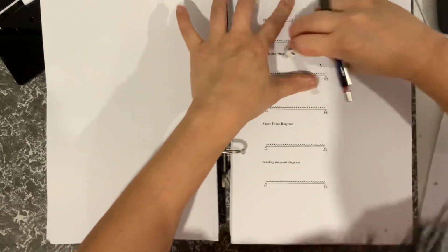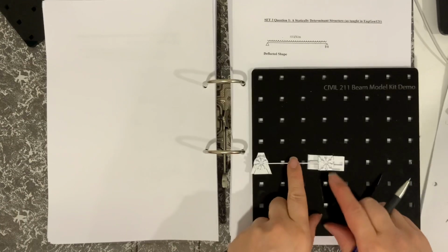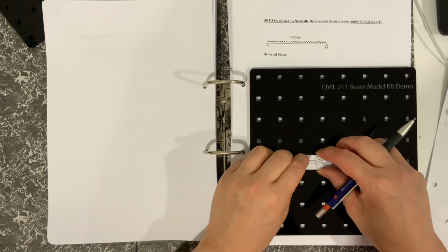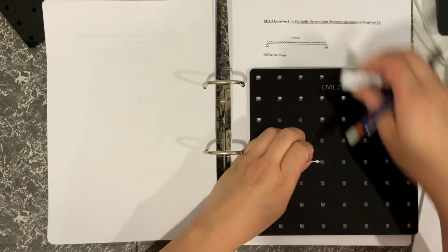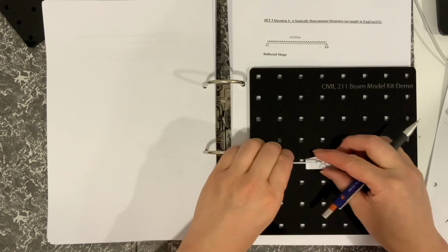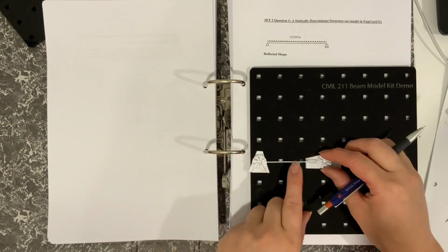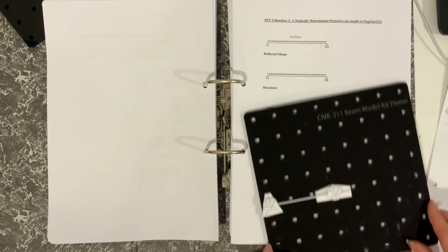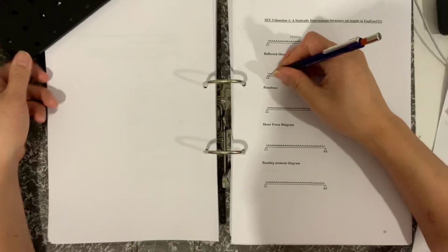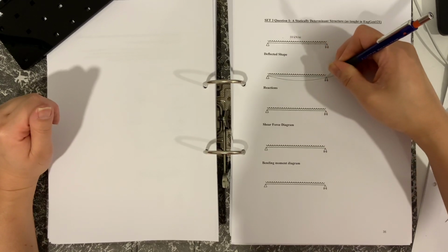So, of course, as I said, I can't demonstrate a UDL using this, but I just pretend it's a point load, and then from the point load I get the shape, which would be triangular, and then I will add a bit of curvature into it, sort of raising the power of x up by 1. So that means that the deflected shape would be like that.